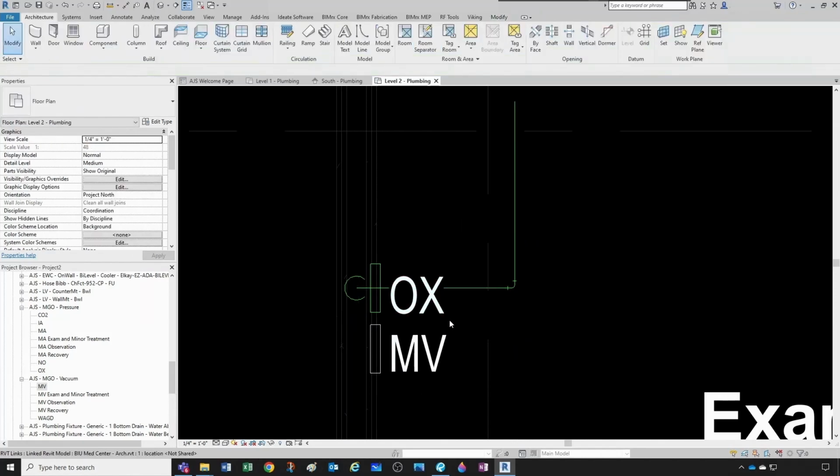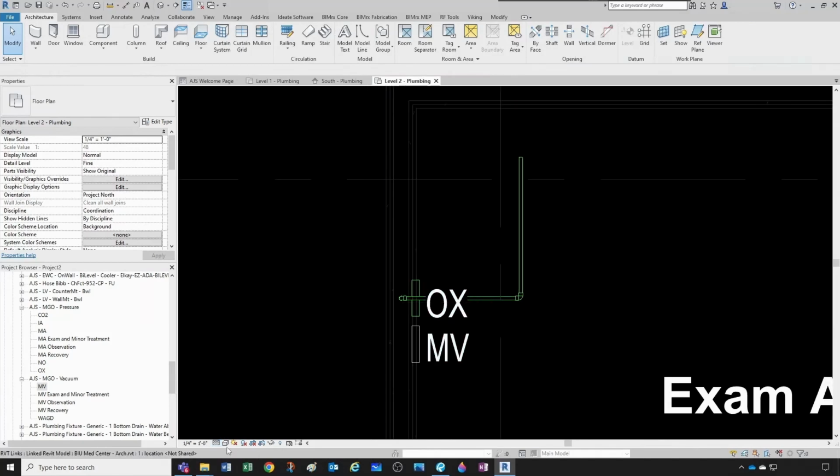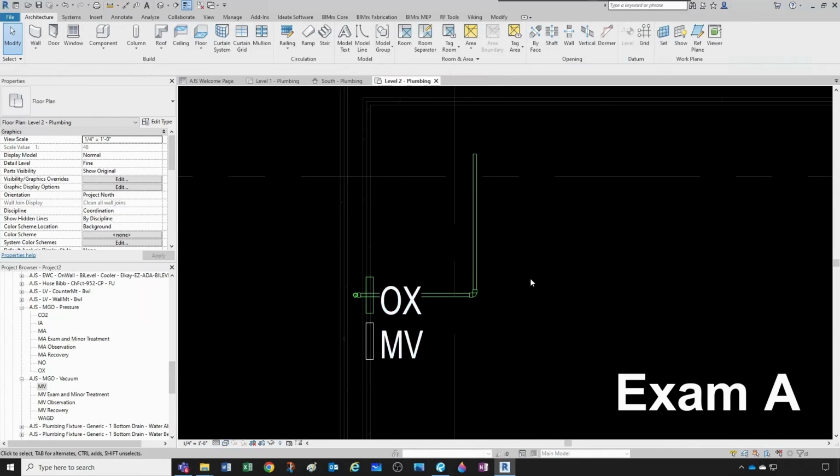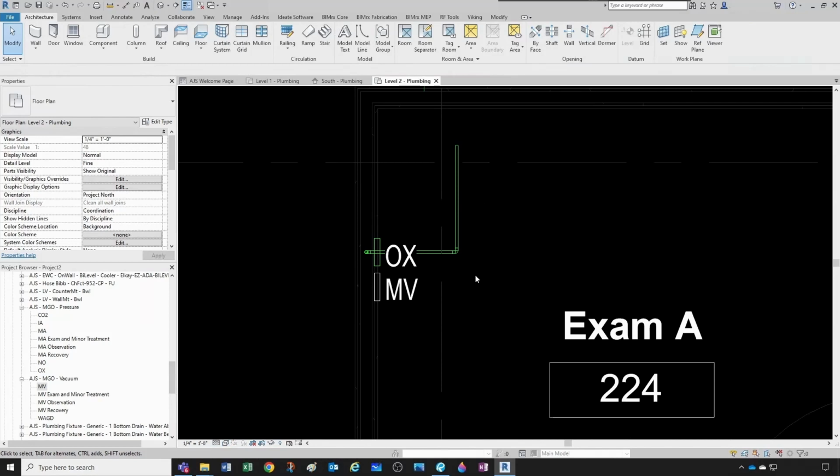I can connect, and you can see how my outlet turned green because it's accepting the system. Since this is a modeling view, I'm gonna change my level of detail to fine, just so that I can model a little bit more comfortably. And instead of shaded, I'm gonna keep it as wireframe, because all this is gonna be just modeling, okay?